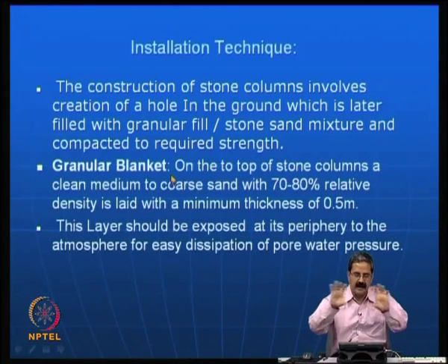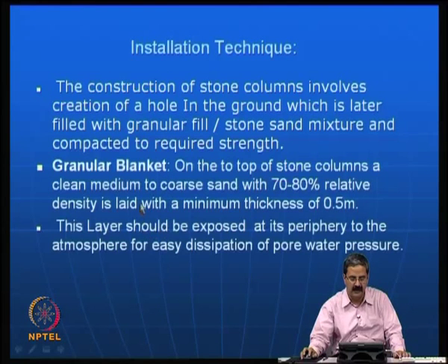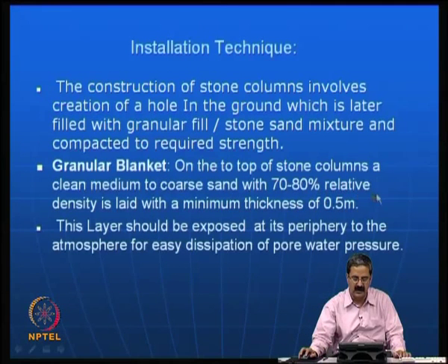You need to have a granular blanket of medium to coarse grain, about 70 to 80% relative density, laid with a minimum thickness of about 500 mm. This layer is exposed at its periphery to the atmosphere for easy dissipation of pore pressure.